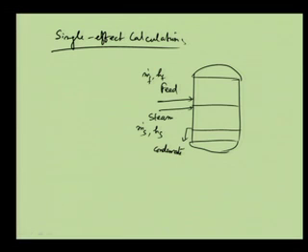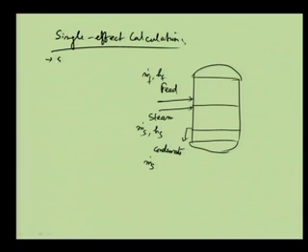And for this condensate, m dot s will again be the flow rate, because whatever steam is entering is getting condensed. Our consideration is saturated steam. The heating medium is the condensing steam, so only the latent heat is involved.